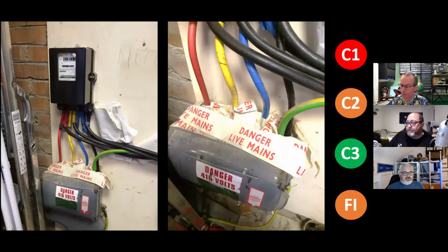Somebody has said the black looks taped too. So those cables coming out of the head are taped. Yeah, so they are phase taped. Okay, red, yellow, blue, black. You can see there's a bit of red peeking between the yellow tape. Yeah, so somebody used one drum of red singles and just taped them up the phase colours. That used to be done a lot. Let's be perfectly frank, that's what people did. It's easier to hold tape than extra drums, isn't it? Of course it is. It's far easier.